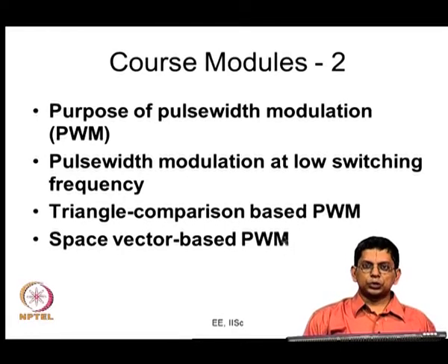Here you use the space vector approach. Instead of the 3-phase modulating signals, you have one revolving voltage space vector. You sample that every subcycle and that gives you the voltage command, and you try to realize that by applying the various vectors of the inverter for appropriate durations of time. And these two are equivalent to a large extent.